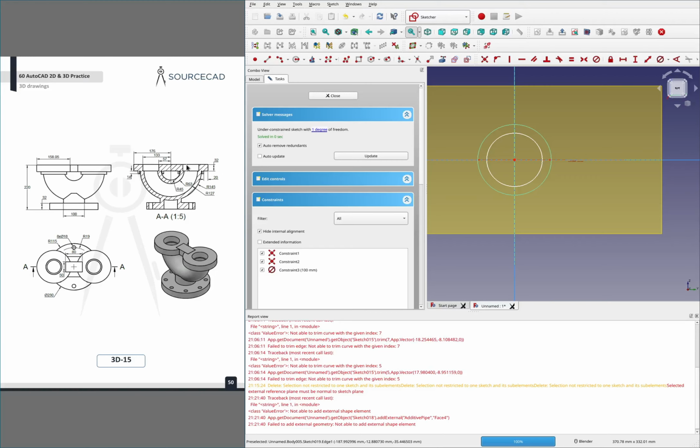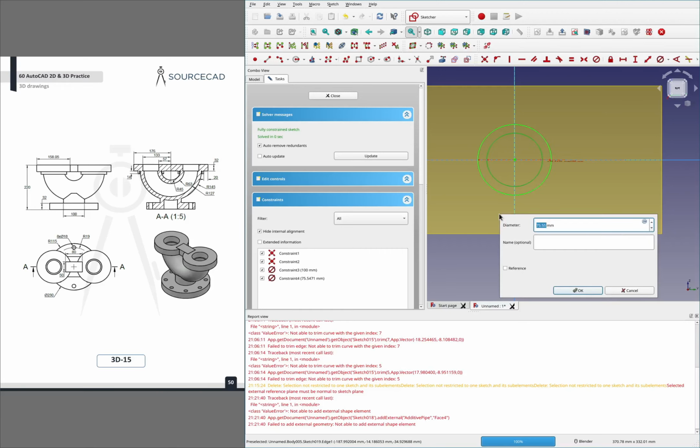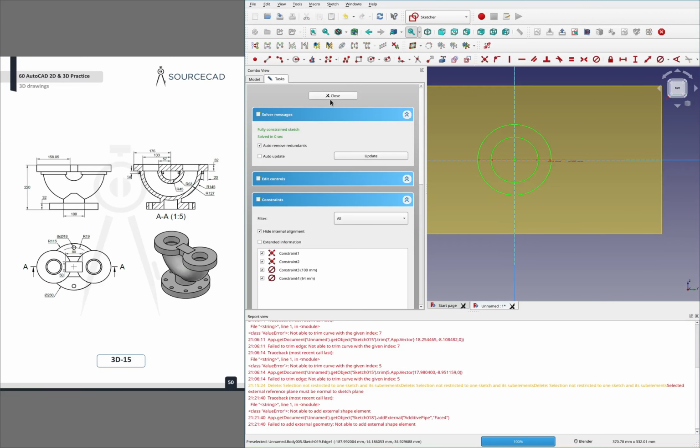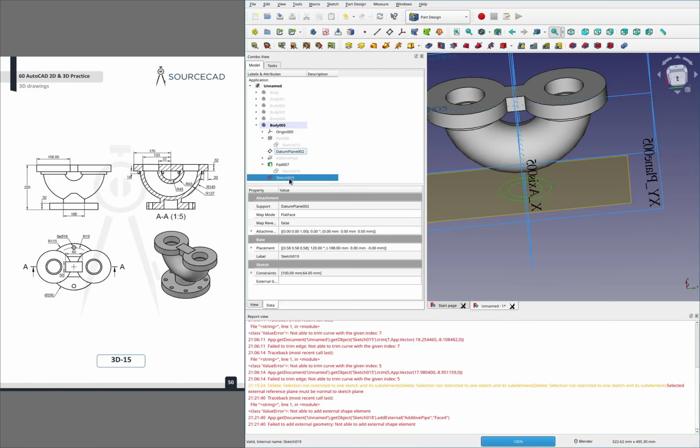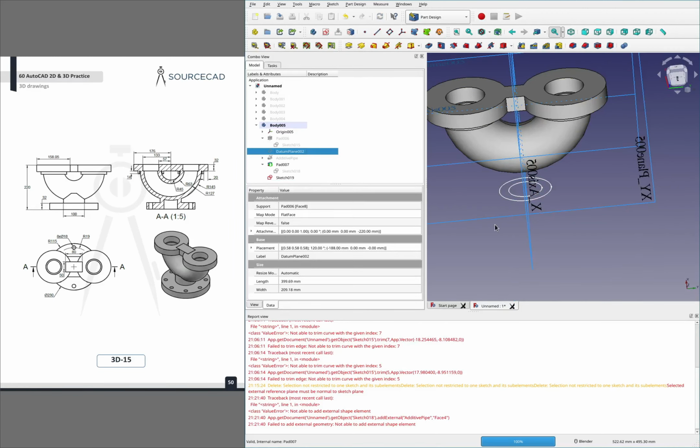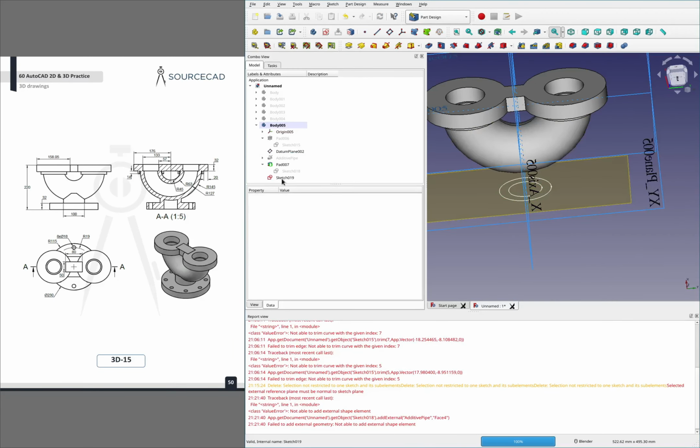We can get the thickness with 145 minus 127, so it's 18 thick. So I calculate that this one also should be 64 diameter on the inside. Okay. We can hide that plane. Maybe we won't hide it.